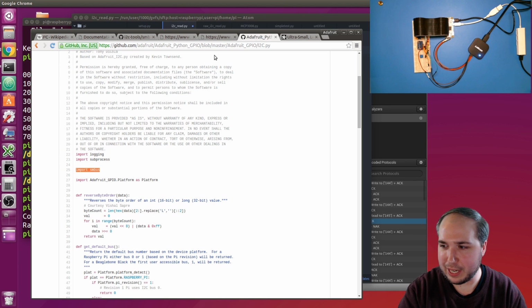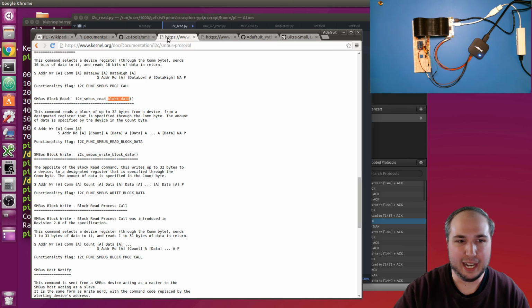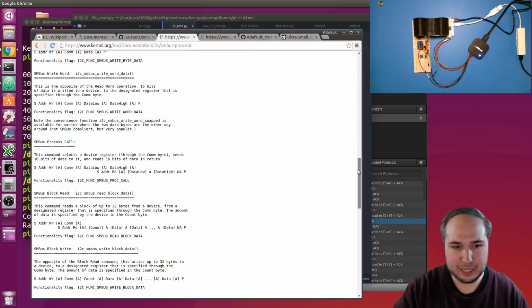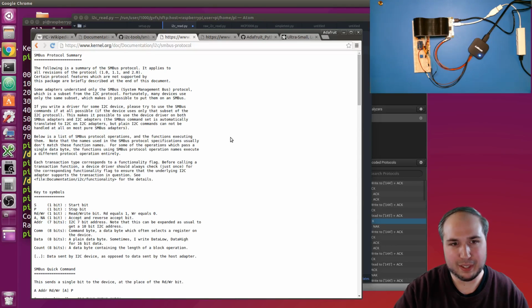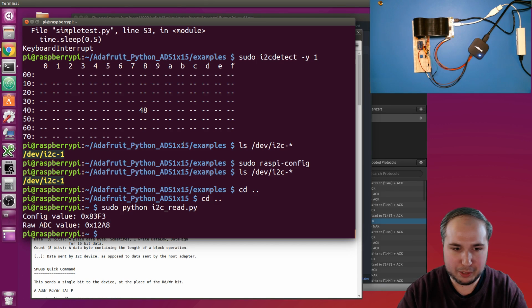Something I wanted to dive into a little bit deeper then is, what is the smbus library actually doing? Like we saw here, it's calling these Linux functions that make these I2C smbus reads and writes, but there's actually something another level deeper that we can look at, and it's the raw device here, the dev I2C 0 bus or 1 bus.